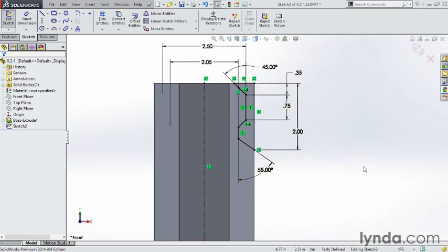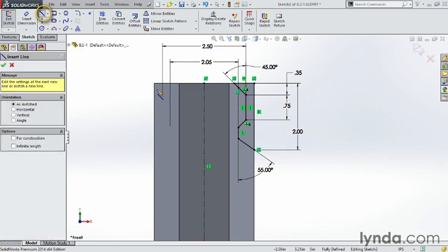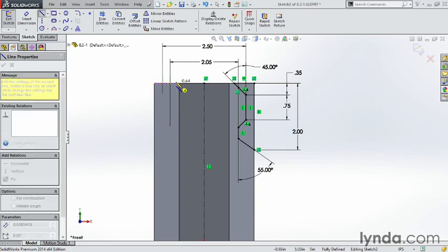Just to give you an example, let's try out some of these sketching skills. Let's go up here to the line command. I'm going to start right on this upper corner and draw a line over to here, draw a line back over here, down to here. I'm just snapping to those corners, down and back over. And then I'm going to drive it all the way back up and close that sketch. So I have one enclosed boundary, all just using the simple line tool.